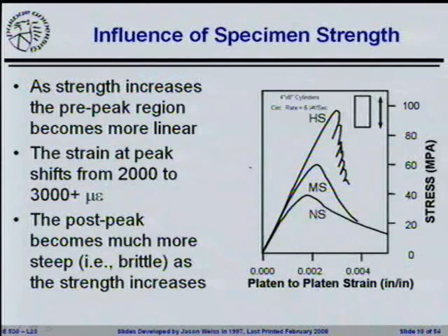Now, a few of the things that we'll talk about as it relates back to testing. As the strength of your concrete starts to increase, you will start to see a different response in the overall concrete. All right, so this is information that comes out of a PhD thesis. And this is a thesis that was specifically looking at topics that are related to how the strength of the concrete influences the stress-strain behavior. The proportion of this line that is linear becomes much, much bigger for the high-strength concrete than it is for the normal-strength concrete.